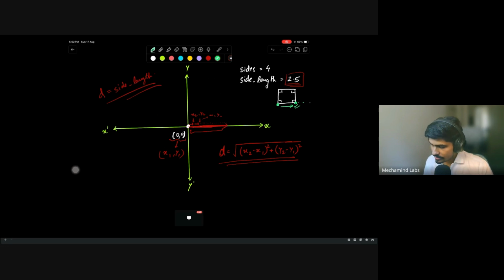How will I stop the turtle? I'll simply put the command linear x velocity as 0. This will simply stop the turtle. And right now we are only publishing linear x velocity, no angular velocity. The turtle is directly moving forwards. So at this point, we will stop the turtle, and then we will ask the turtle to rotate like this. So it makes 90 degrees. How will we do that?